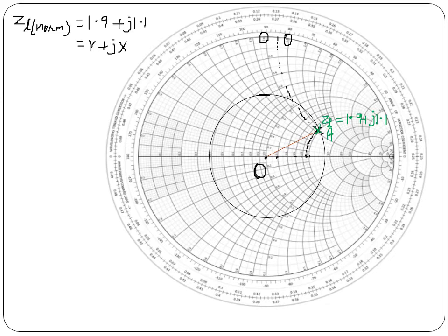Now we have to find the admittance corresponding to the ZL impedance on the same chart. For that, the impedance radius OA is extended to B through the 1.0 center point until it intersects the VSWR circle again.